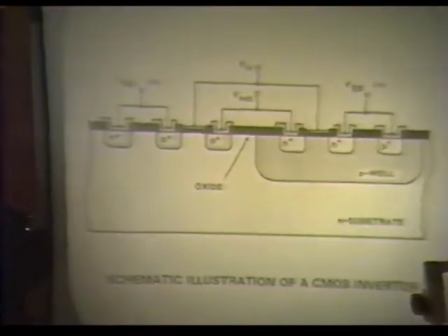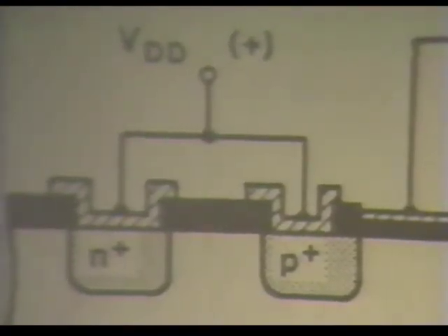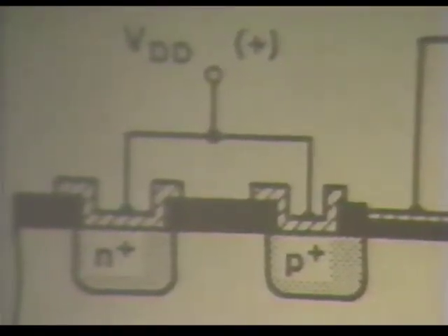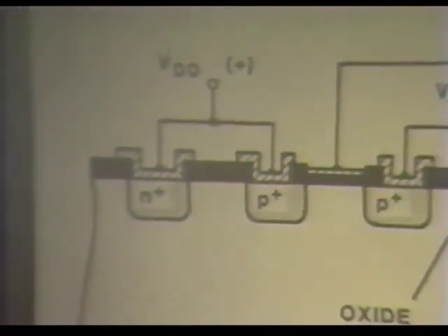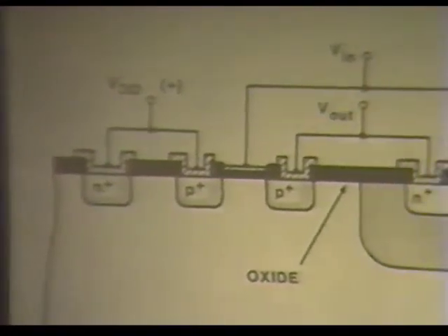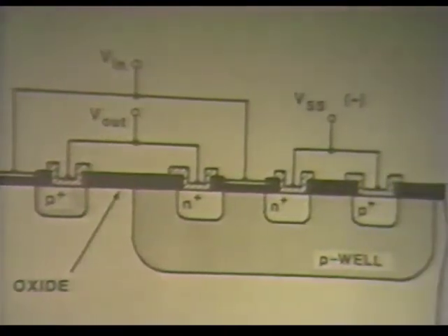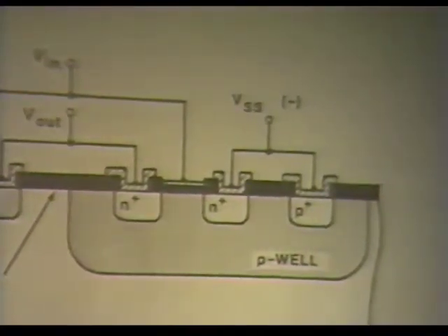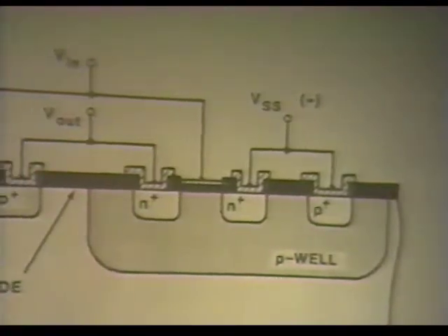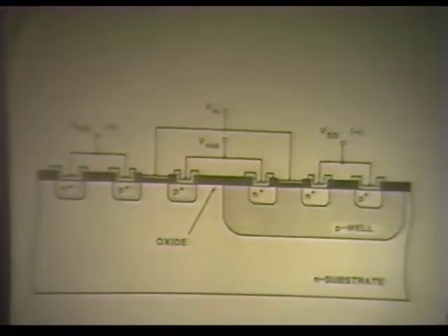And I'm going to give you a blown-up version here, but what happens there? Well, the gammas or the X-rays go whizzing through the oxide. They create electron-hole pairs. Now, an oxide is different from silicon. Silicon is a semiconductor. It conducts pretty well. The electrons can move through that pretty well, but an oxide is an insulator. It doesn't conduct charge carriers very well at all, as you've been told, I'm sure. And it moves the electrons pretty well, but the holes don't move very well at all.